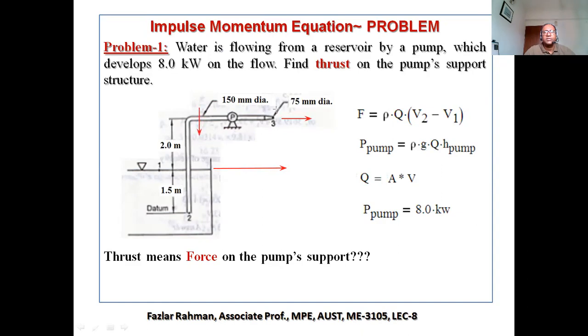So right over here, even though we are getting the same fluid, the same Q, the velocity would not be the same because the area of the nozzle is smaller. So over here the velocity will be high, and before the pump the velocity will be low. So what are they saying?